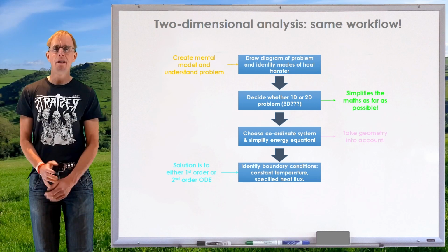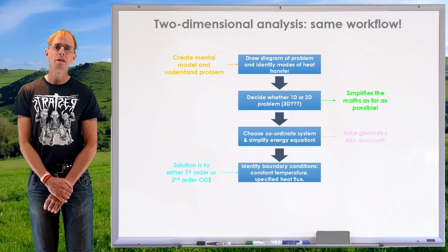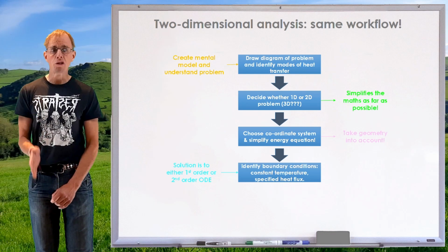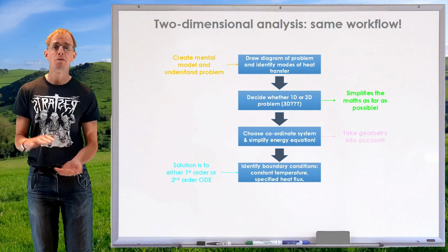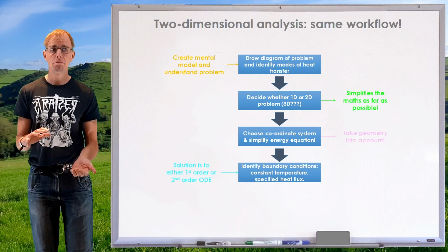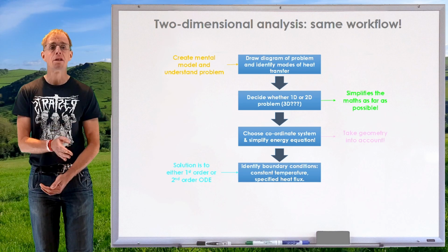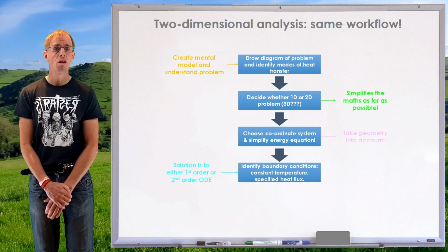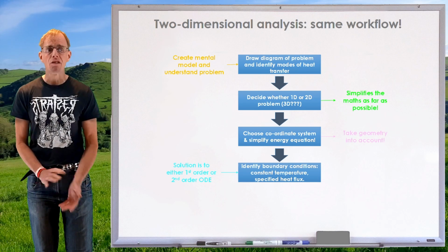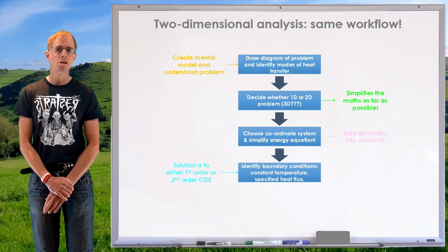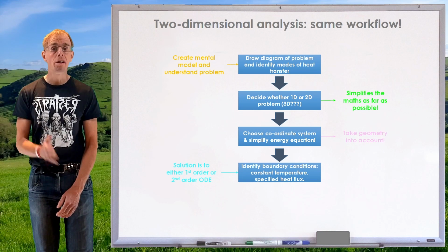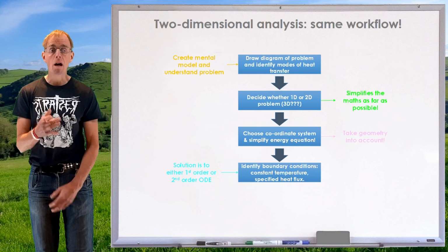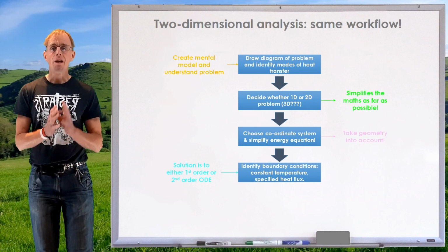So for example, an extruded product leaving an extruder, we might know what the die temperature is. That's probably set. We've probably got convective heat loss from surfaces. Then we need to think about what's happening at the far end of our extruded product. We might make a somewhat circumspect or crude assumption that the temperature gradient falls to 0. Or the temperature gradient is controlled by a convective process. Either works.